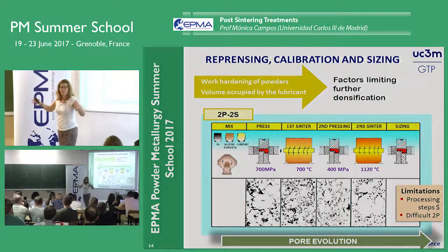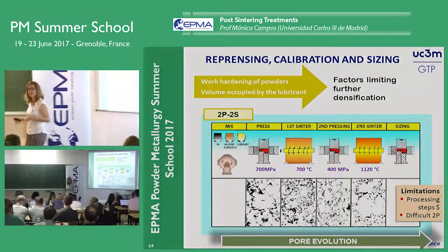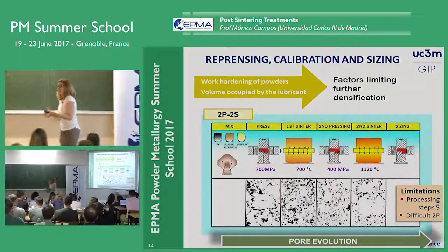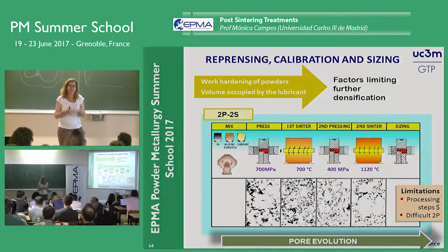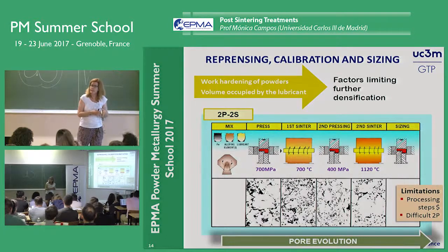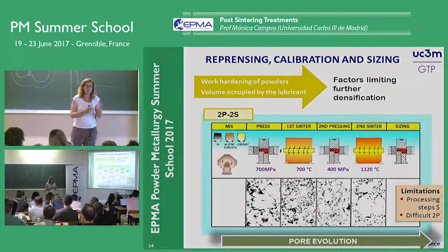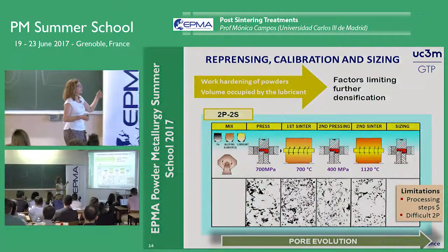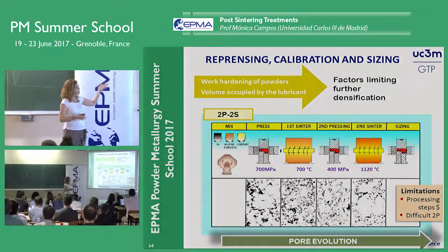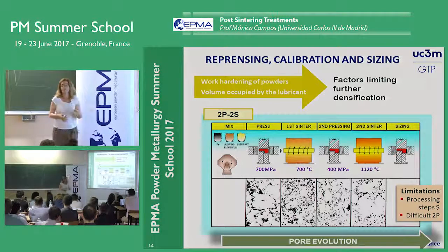Well, there are some press machines that maybe are able to press it. But normally it's easier if we work with softer materials. Then in the first sintering step, it's better to control the temperature below carbon diffusion. Carbon diffusion should be higher than 700, 750, more or less.